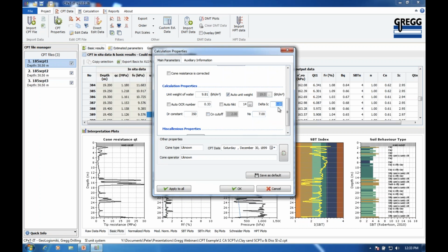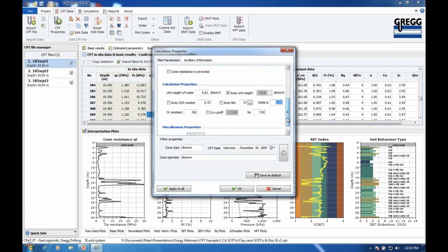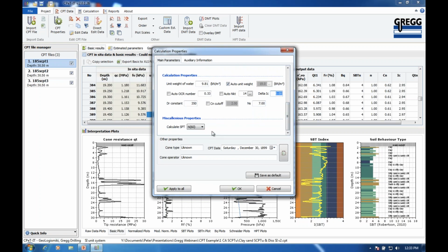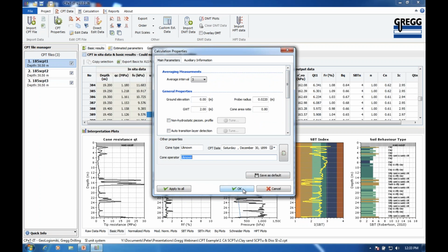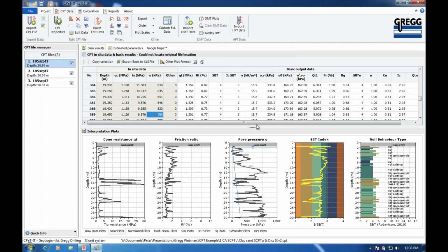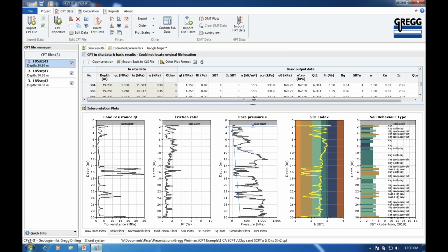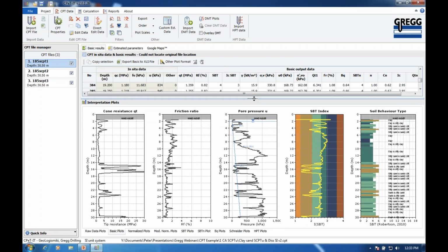And there's also a little button up here which comes from ground improvement to make a slight shift in the IC. And we covered that in the webinar on ground improvement. Then there's one little button down here that it's also going to estimate the SPT-N value, and it defaults to N60, but you can look at N160, the normalized N60 if you wish. So those are all the parameters that allow all the interpretation to be done. So interpretations like for modulus, it's built in, so actually there is no constant, so you don't get to change it very much. So I'll go through the plots.